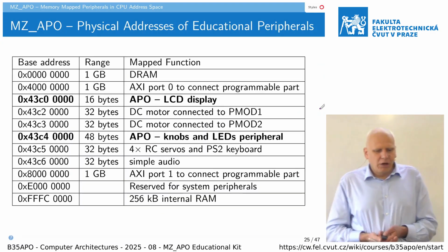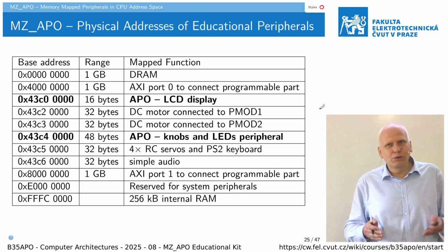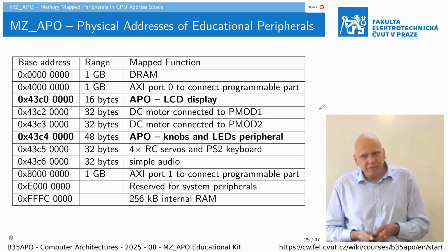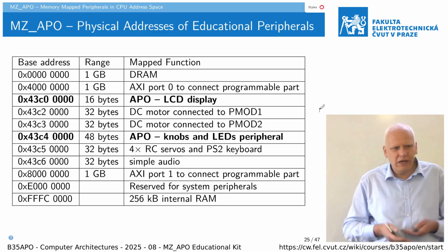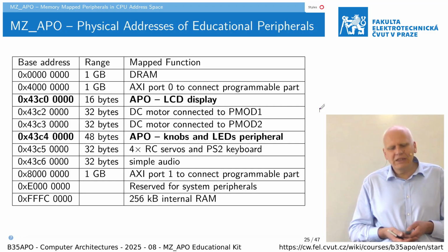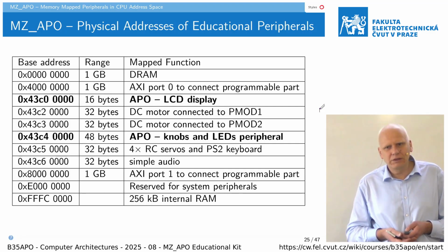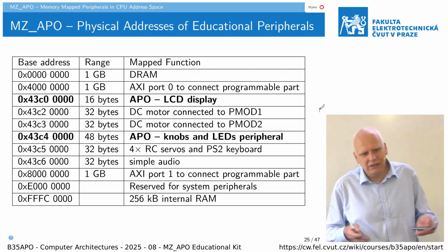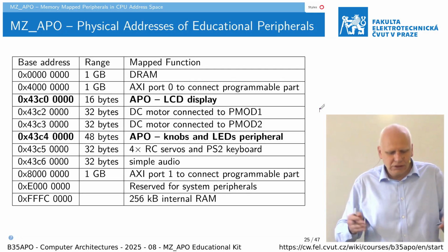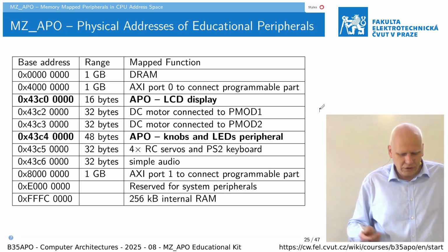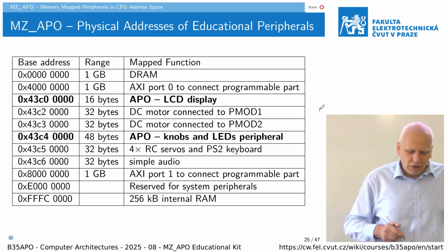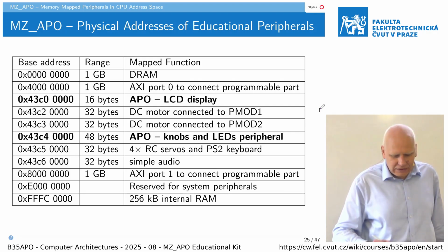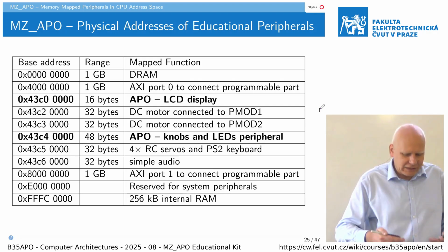Okay, so what do you get? Basically, if you want to do something more complex, it is possible to design your own peripherals. All the tools are available on the computers, but it takes relatively long, because even the compilation and synthesis of the design takes something like 20 minutes, and you need to know the VHDL or Verilog language and so on. So for your simple task, you have some peripherals which we have prepared, which are simple, really educational peripherals.